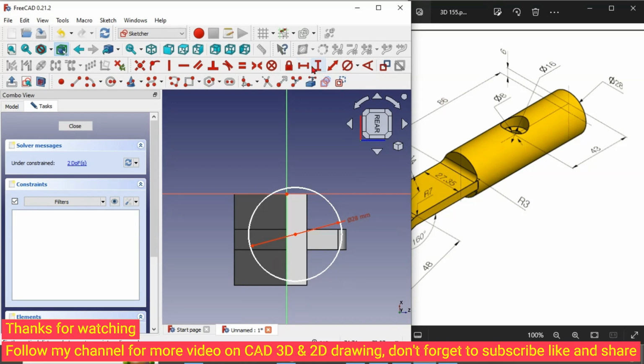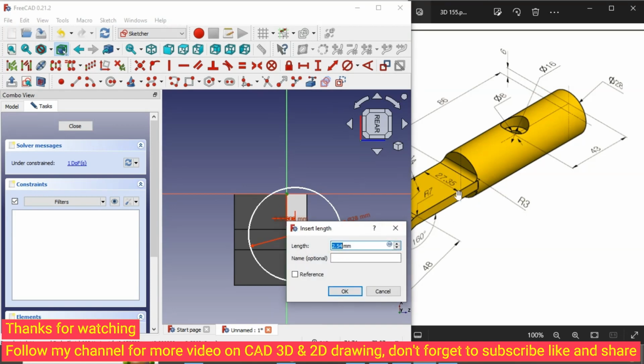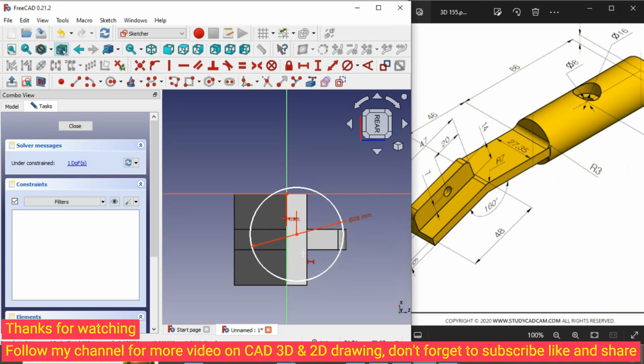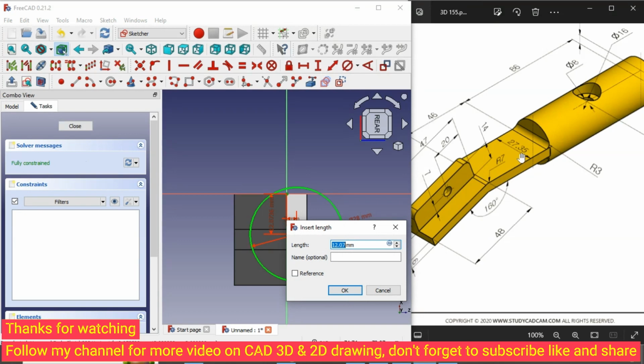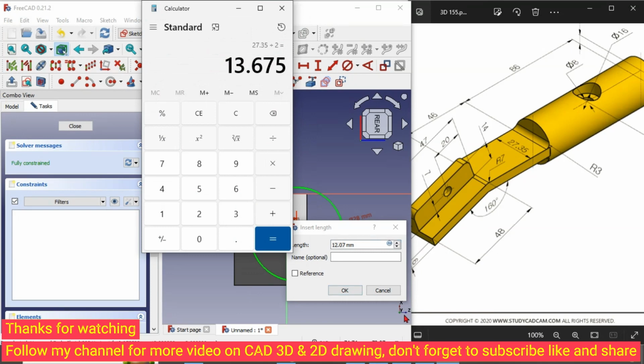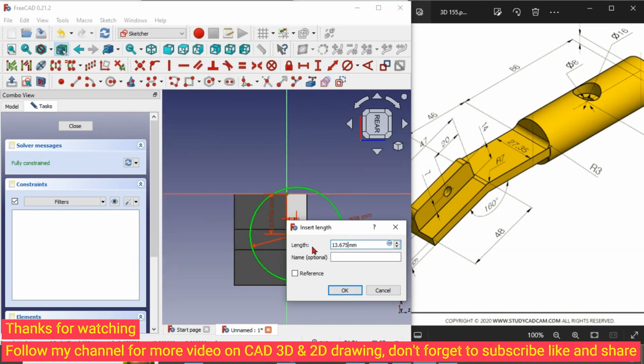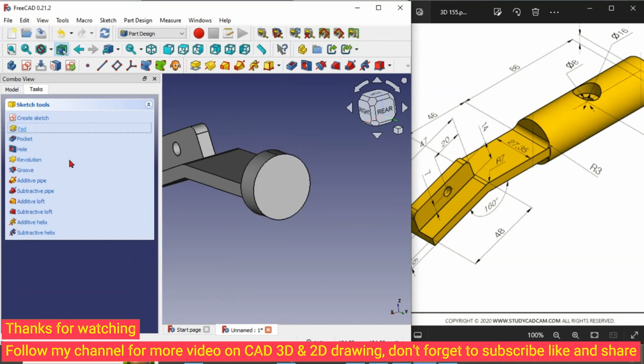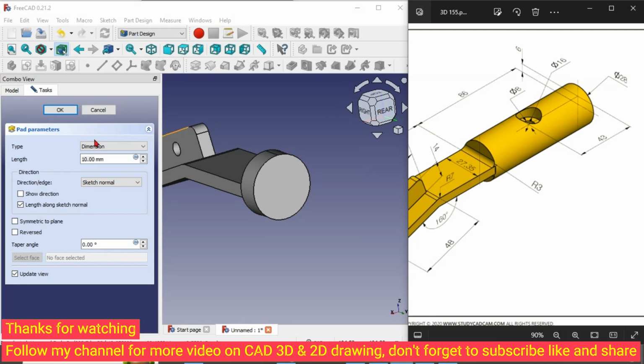Then we set the distance from the reference line. For the horizontal, see this block is 6mm thickness, so we divide by 2, which should be 3. The vertical distance from here to here is 27.35. We divide by 2, so we take this dimension here. Okay, we stay in the middle, close, set a pad. So the distance is 86.